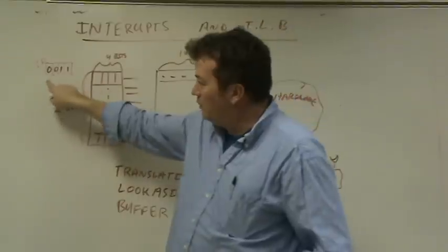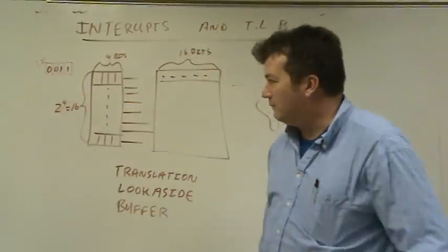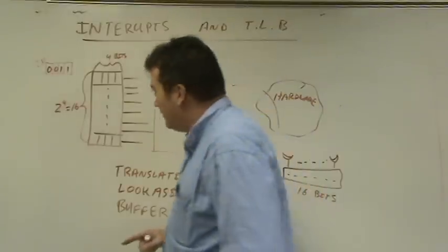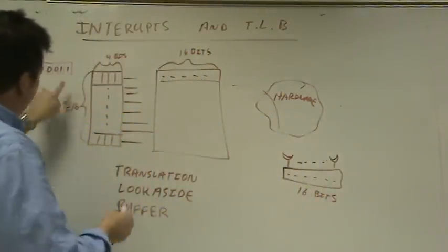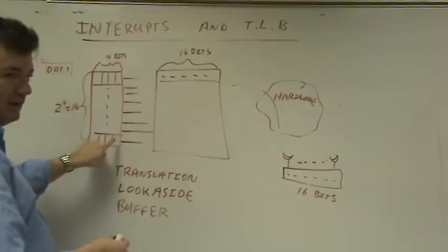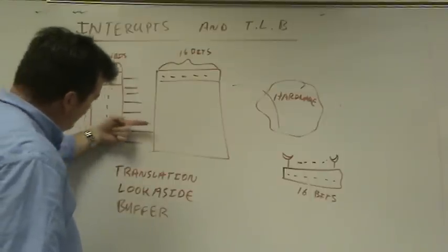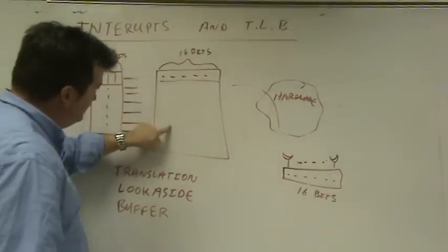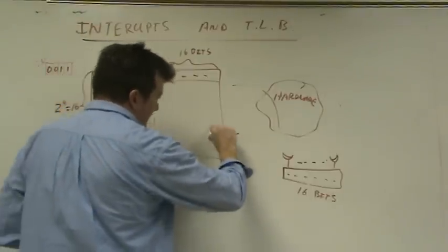These bits will all be ORed together, and if any of them is on, that means we have a problem. If one of them is on, that electricity will come in and cause us to check, do these 4 bits match any one of these 4 bits exactly? If so, that'll send power into this table, which will then take whatever address is here and copy it to here.